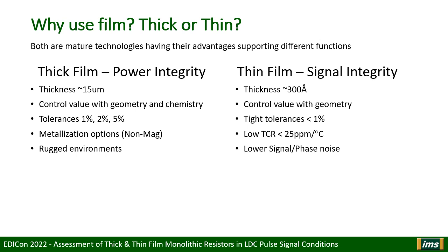In matching or feedback networks that are expected to undergo thermal cycling, thin film parts with low thermal coefficient of resistance can help keep signals stable across wide temperature ranges. Some of the challenges designers face everywhere is knowing when to prioritize a part for selection when competing properties arise, given a set of design goals and constraints. The answer to so many questions in this field begins with, well, it depends.